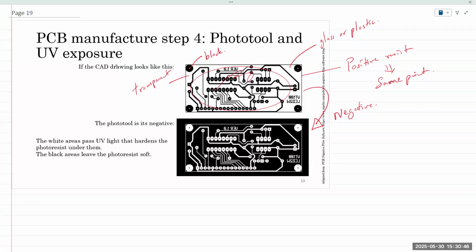Does that make sense? A negative photoresist, everywhere the light hits is hardened, and everywhere that is blocked gets washed away. And so areas that are blocked, like these, areas where the light hits will harden on the surface, and hence you get the opposite pattern.